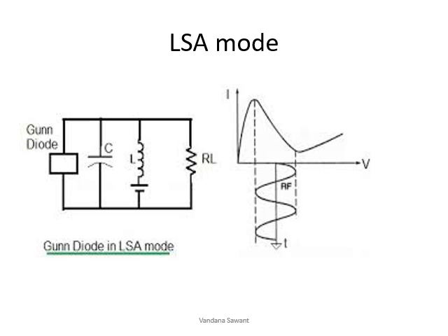So whatever current is moving towards the anode, the device is always kept in the negative resistance region. So finally we can use it as an oscillator, and we continuously get an output current, as shown in this VI characteristic diagram.